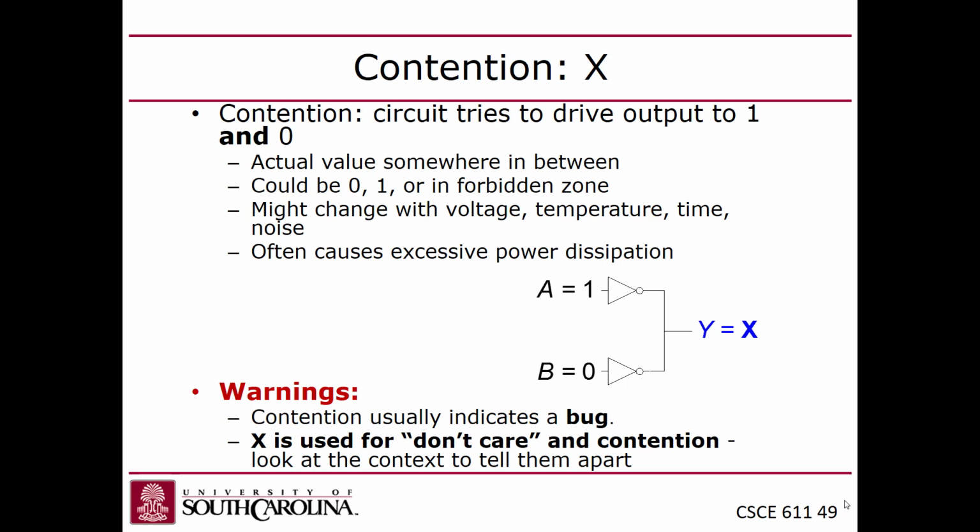The other reason you might have an X is if you have a value that's undefined, which they don't talk about here because that's something that will be addressed in the sequential logic section. But if you have a memory or a flip-flop or some kind of memory element and it hasn't been initialized, and you go to simulate the circuit, the period before you initialize that memory, you get X's. That just means unknown, right? It doesn't know what it is, right? In reality, it would come up as a random value. But in a simulator, they mark it as X, so it draws your attention to that.